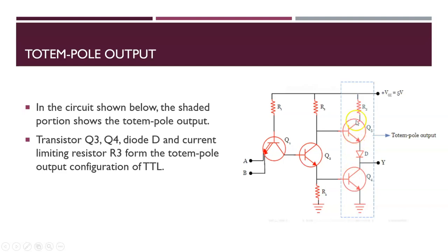The next thing over here is the advantage of this circuit. In this circuit, usually when the transistor Q4 is off, the output should charge from 0 to VCC. When the output is getting charged from 0 to VCC, it will charge with a time constant equal to RC. Whatever the load capacitance C is, we won't change the load capacitance. Only the resistance has to be changed.